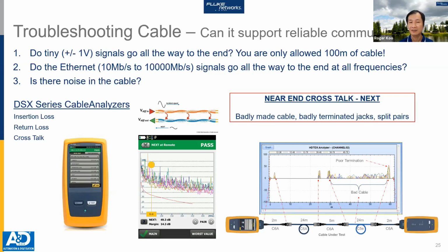Sometimes when you dial a number, you could hear other parties speaking on that line, which is not what it's intended for. That's crosstalk. That means that when a signal is traveling down one wire pair, it crosses over to another wire pair. Thus, you hear interruptions. This is known as near-end crosstalk because it happens at the near end.